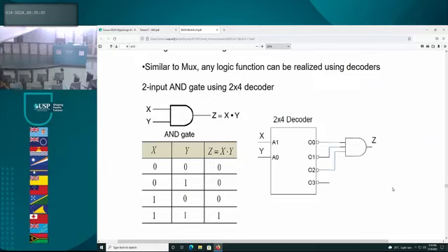I just spoke. How many ways is there which we can build an AND gate? Firstly, so let's say you go to the technician, and the technician says, or the shop says, sorry, no AND gate because of the war in Europe. There is a shortage of AND gates. All right, so what do you do? You say, all right, first thing you're going to ask, do you have a NAND gate? Okay, because you can build an AND gate using NAND gates. And he says, sorry, no NAND gates. Or they say, we got NAND gates, but they're already booked by some other students in 4th year. Then you're going to ask for NOR gates, because you can build an AND gate using NOR gates.